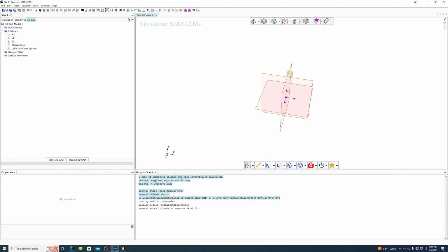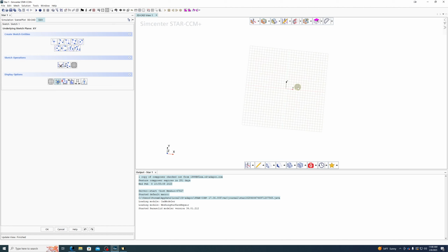So I'm going to start, just as a brief example, and we won't go into this in a huge amount of detail because it works very similar to most other CAD applications, and you're probably familiar with at least one that works like this from previous classes. We're going to hit create sketch on the XY plane, and we're going to get a sketch.